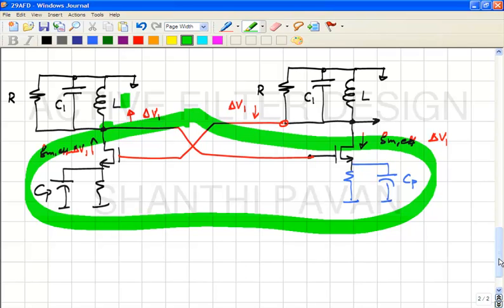It is quite likely that when you put two transconductors in a loop to form a gyrator for differential signals, the positive feedback loop, which is automatically formed for common mode signals, can make the gyrator unstable even though the individual units are stable. Right? You understand?